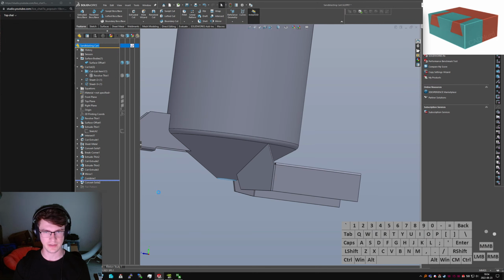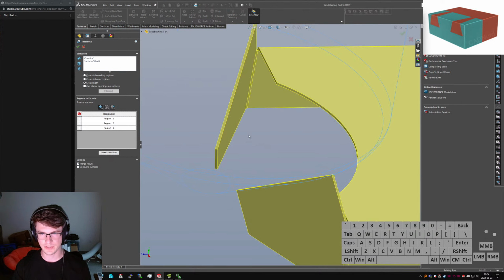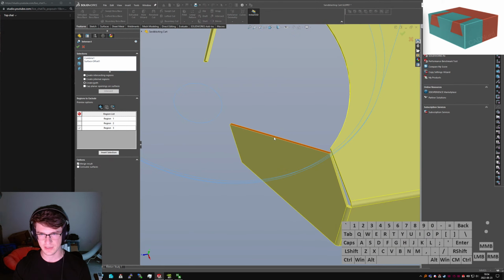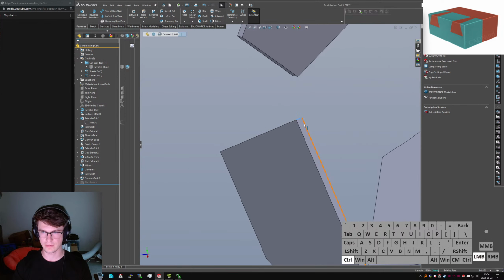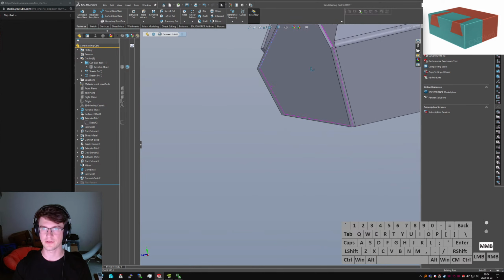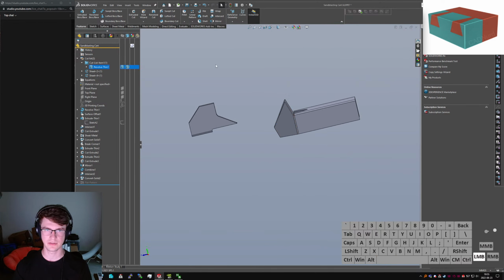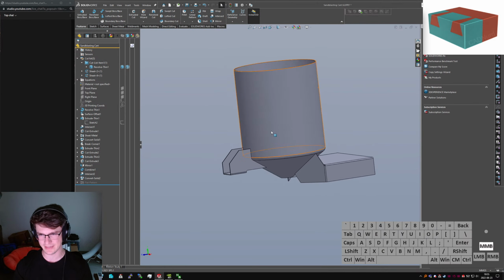In fact, we can go back and do that with the combine. We can say intersect, and I imagine we'll have some regions to get rid of up here. So if we get rid of this guy, and say consume surfaces, because this is the last intersect we're going to do, if we convert to solid, now we have straight 90 degrees, straight 90 degrees, and they're all sheet metal parts. Excepting the obvious one, because that'd be really difficult to do in sheet metal, and I'm lazy.